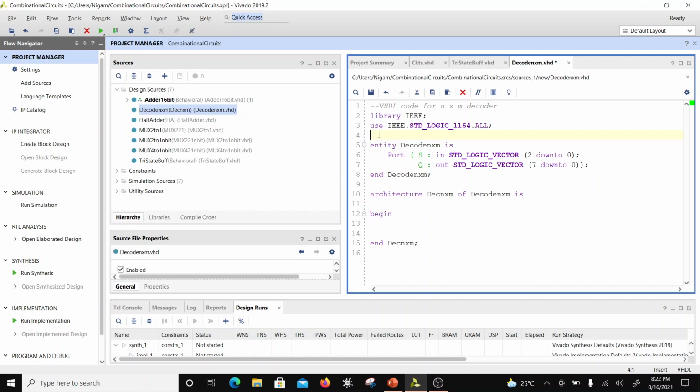And that's why I have to use a process block, which is a concurrent block with a sensitivity list. But then the statements inside that block are all sequential statements. Only simple assignments are allowed. Okay, conditional or selected assignments are not allowed. Somewhere Douglas Perry makes a mistake in one of its examples. So be careful when you read that.